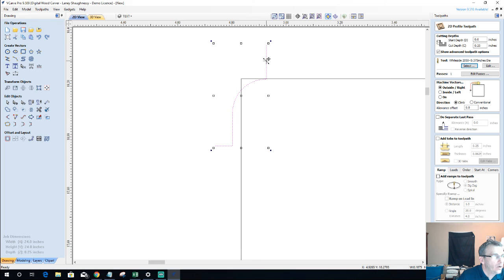Well, if I go on the outside of the line, then the toolpath is going to be cutting on the right side of the bit, meaning that the cutter is too far away. So I need to offset it inward by 1/8 of an inch, and my cut depth is only 1/4 of an inch. So that way I'm rounding off that edge.